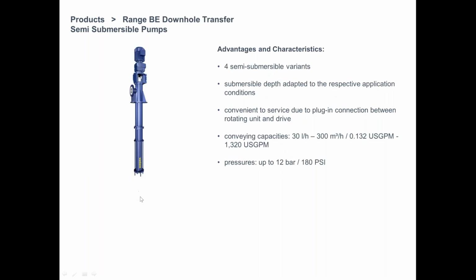Fluid will be pulled up as the pump runs in reverse. Fluid will be pulled up into the pump and discharged out of this branch right here. The motor and seal would be above ground. Every other part of that pump could be submerged. These are used predominantly in the oil and gas industry, but are now being used to replace many, many centrifugals in the mining market.